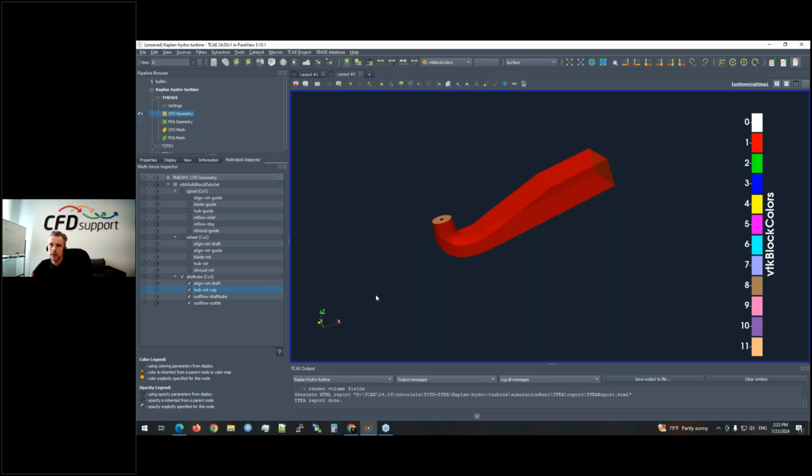And I hope it's clear that I'm talking here still about just the surfaces. I'm in 3D, but I'm talking about surfaces, right? The volume mesh, the cell mesh, will be created later in the process. But again, it's important to say that this pre-processing part, this cleaning part, is extremely important, because it sets all the aspirations and all the expectations right here in the beginning.